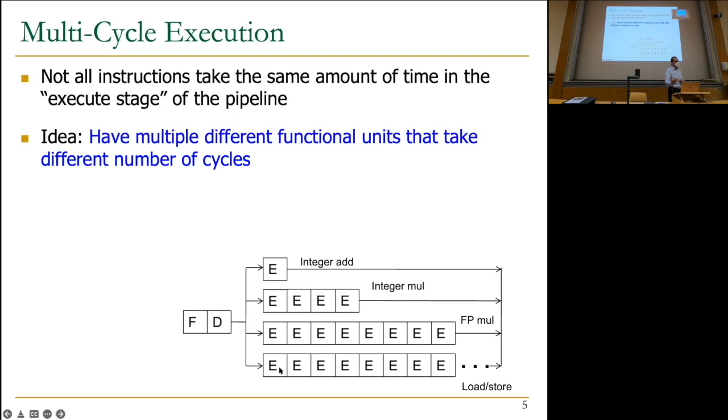And if you look at this, then you have a problem with this picture, because you fetch and decode instructions in order, send them into the execution unit in order, and one instruction takes, let's say, 60 cycles to complete. Another instruction that comes after it takes 1 cycle to complete. So what do you do in the write back stage, basically? These execution units can be pipelined or not pipelined. It's not as important. The important thing is they take 60 cycles. Pipelining this, as I show you over here, actually is better for throughput.